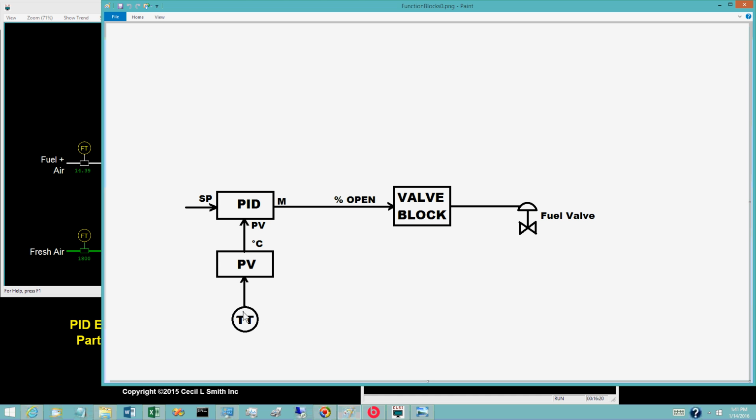In process applications, the future is inputs in the form of digital values from smart transmitters. However, 4 to 20 milliamp inputs remain common, and other types are also encountered. Digital controls begin by converting each input to engineering units. To perform this conversion, a PV block must be configured for each input.